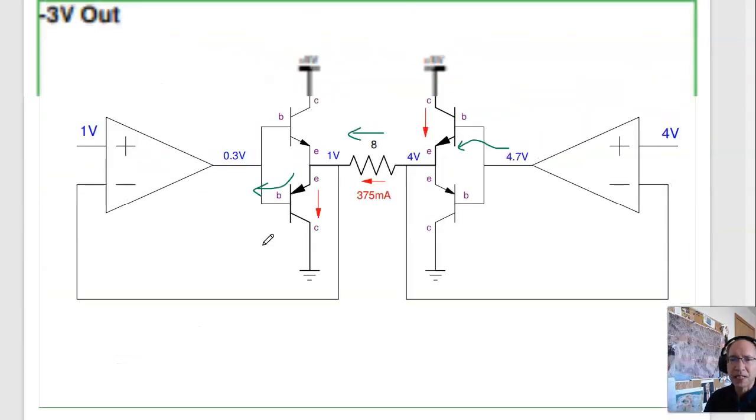So I can't actually get plus minus 5, it can be like plus minus 3 volts out with a single 5 volt supply. Not quite the range because I can't get to 5 volts directly because you lose some voltage through here. I won't quite get to ground exactly because I have some voltage drop across here. So it's more like 1 to 4 volts relative to the load, plus minus 4 volts out with a 5 volt supply.